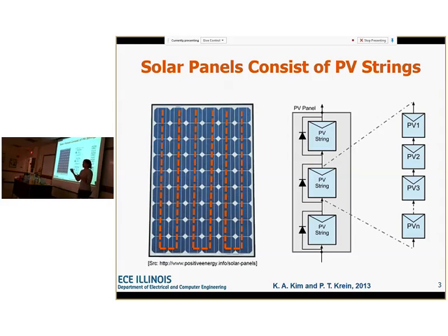Then around each of those strings, you have a bypass diode, which, if you're familiar with photovoltaics, is what they put around it to attempt to protect against hot spotting. But some of the modeling research that I've done has shown that you can still get hot spots that form within, even if there is a bypass diode, which has been shown in a number of studies. So this is still a problem. It's not completely conquered by the bypass diode, although it does help. So we're always dealing with strings of PVs, and really it comes down to this. This is the culprit.